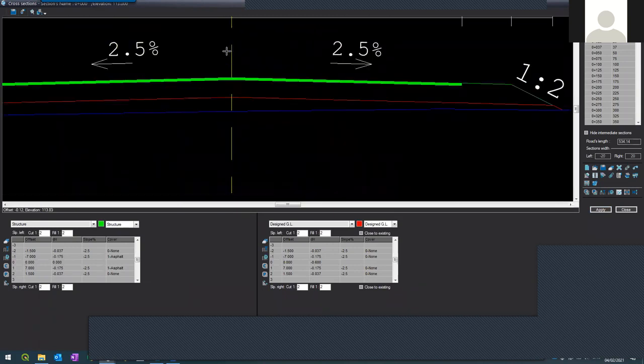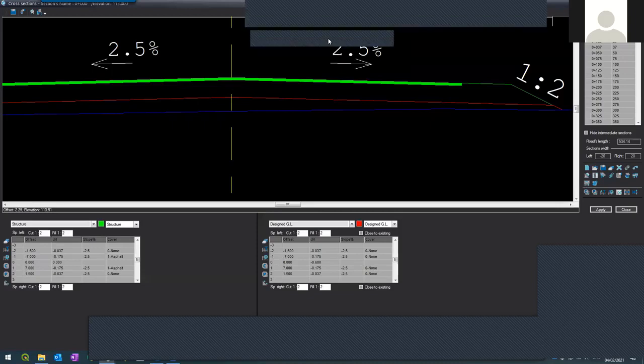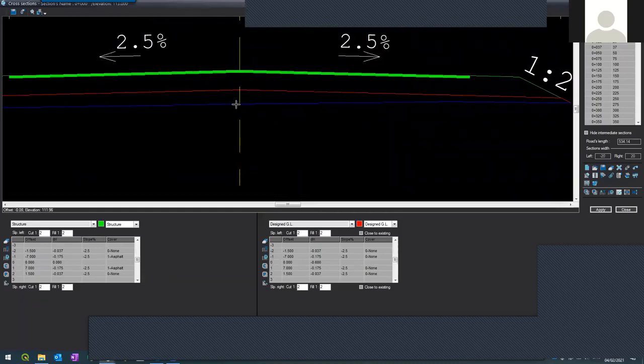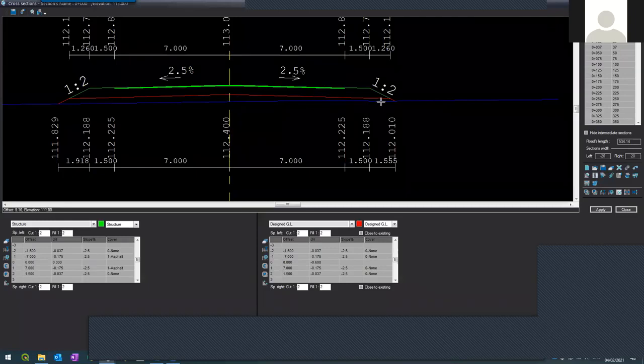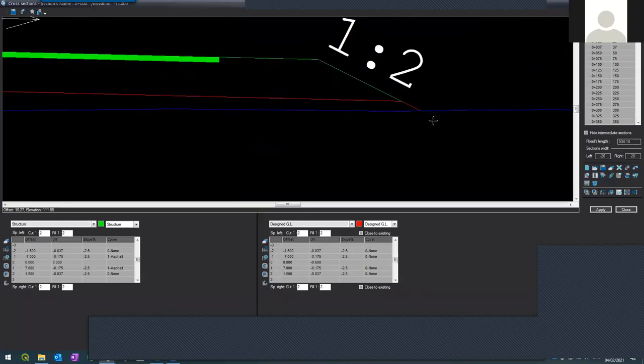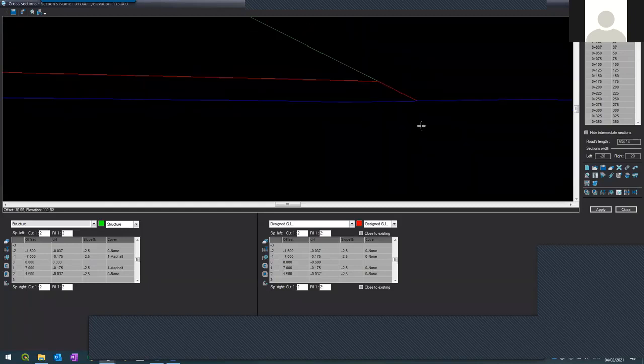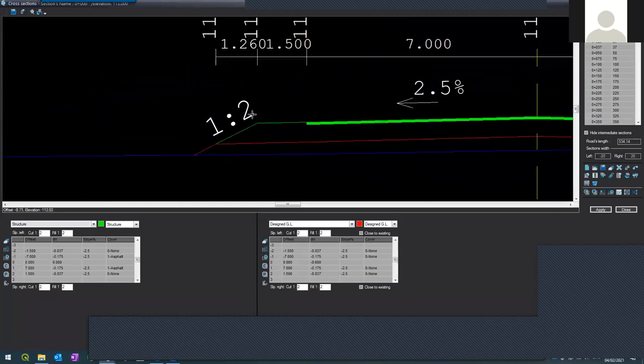Here it is. Okay. So now this is the 1 plus something meter which I took up. So now this is my starting point. I'm above, I'm filling. So this is the top level, the road. This is the earthworks. This is the existing. Now the software automatically recognizes that I'm in a fill situation because of this template, so it went by 1.2 for the filling. Same here.